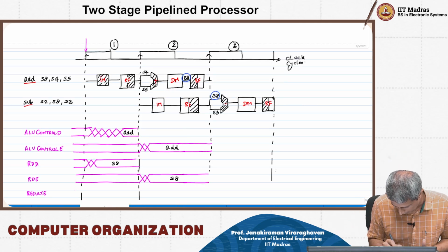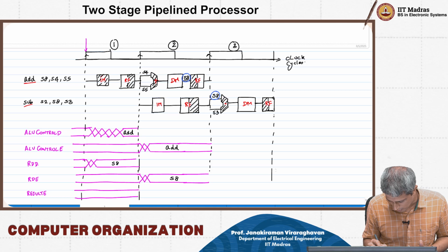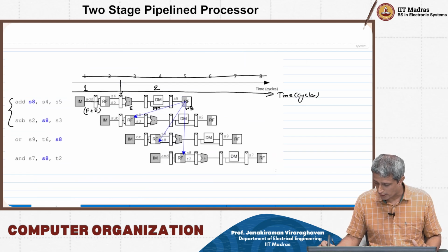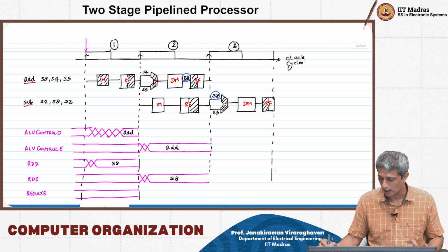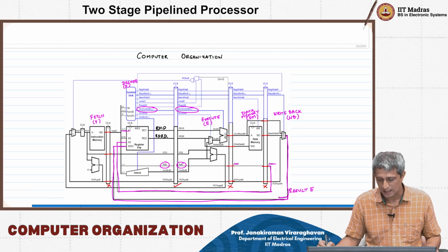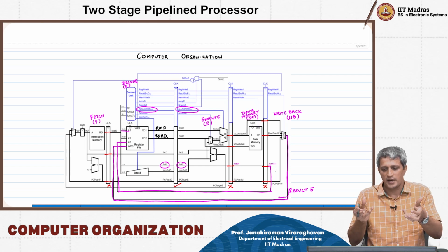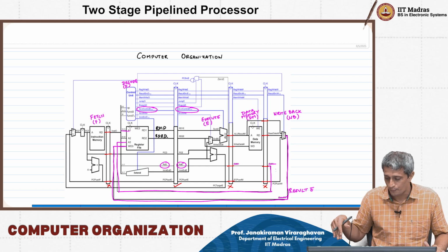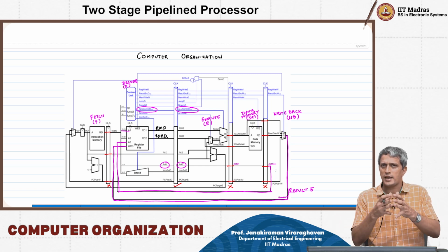What this is in the previous stage I do not know, but the result E here is going to take some time to evaluate, because on the second clock edge data is getting latched for RD1E and RD2E, then it's going to go through the ALU, then the result is going to come out through that MUX, and therefore it will take some time.